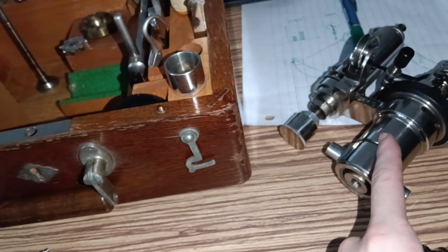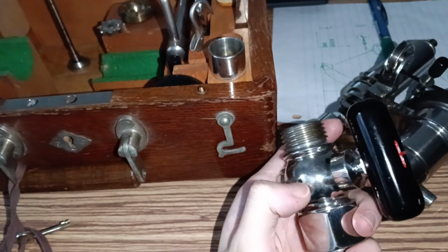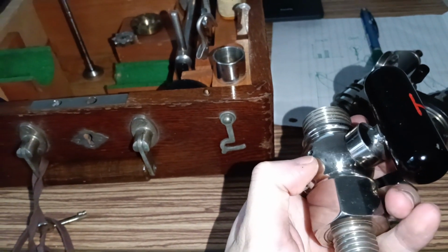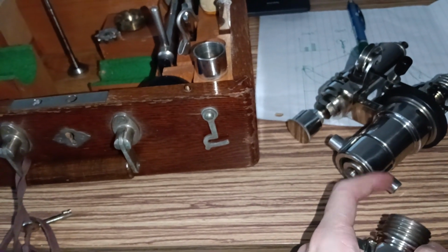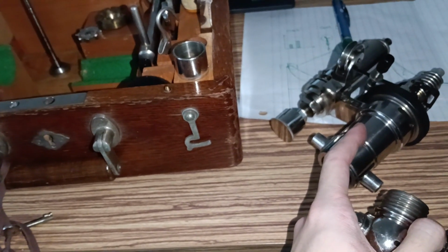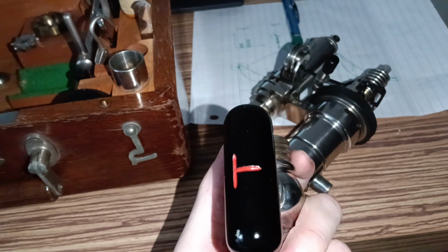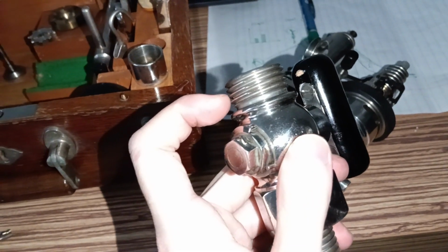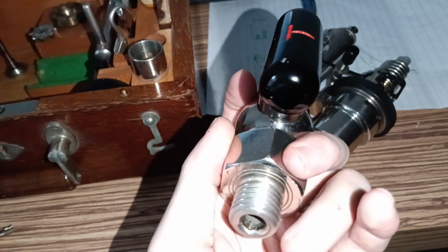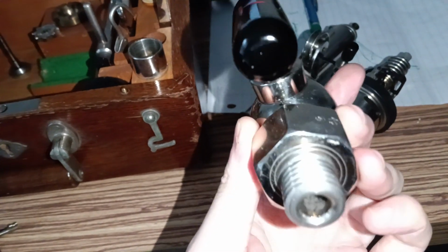If you close it, this upper part, which is connected to here, will be connected to the release hole, which releases the pressure inside the measurement chamber. After that measurement, I understand why: in some old engines they don't have this hole in their indicating cock, and if you disconnect this directly, the engine would shoot it off and propel it at a very high speed.